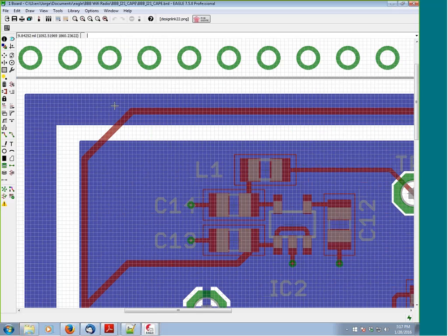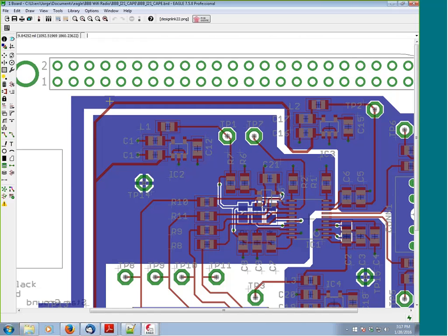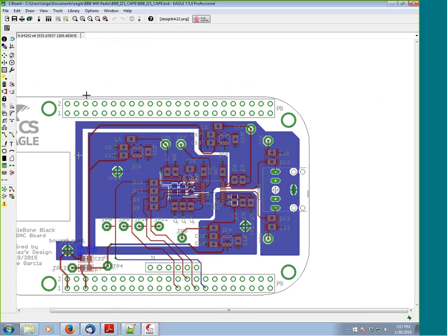So in this case, I have 80 mils. According to that rule, which is basically the limit here, I could run 4 amps through this and I wouldn't get an appreciable drop. So because I'm running such little current, it's not too big a deal. And the resistivity of this segment isn't enough to pull the ground potential very high anyway, to be very different than the rest of them. So for the circuit, it works.